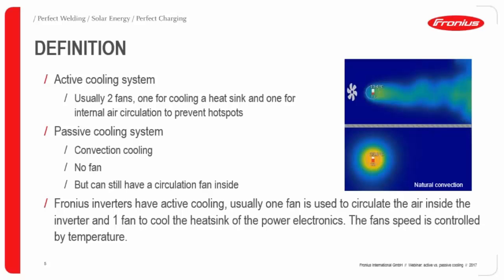Usually there is no main fan with passive cooling, nevertheless there can still be a fan built inside the inverter to circulate the air inside, also to prevent local hotspots.